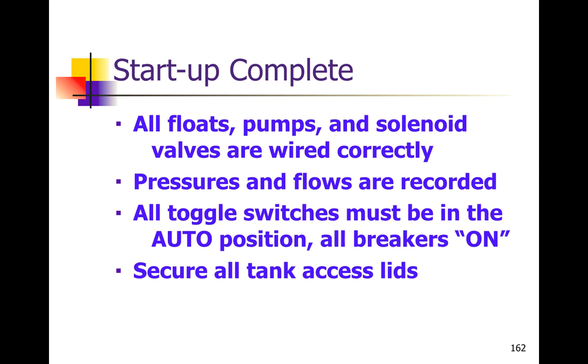Now you've done the complete startup, all the floats, pumps, solenoids, valves. We know that they're wired correctly. If there was a problem, we've identified it, we've got them corrected, we've retested. So we know everything is done properly. We have our pressures and flows recorded. All the toggle switches will need to be in the auto position, and all the circuit breakers are going to be on. And I would suggest doing this even if the house isn't going to be occupied right away.